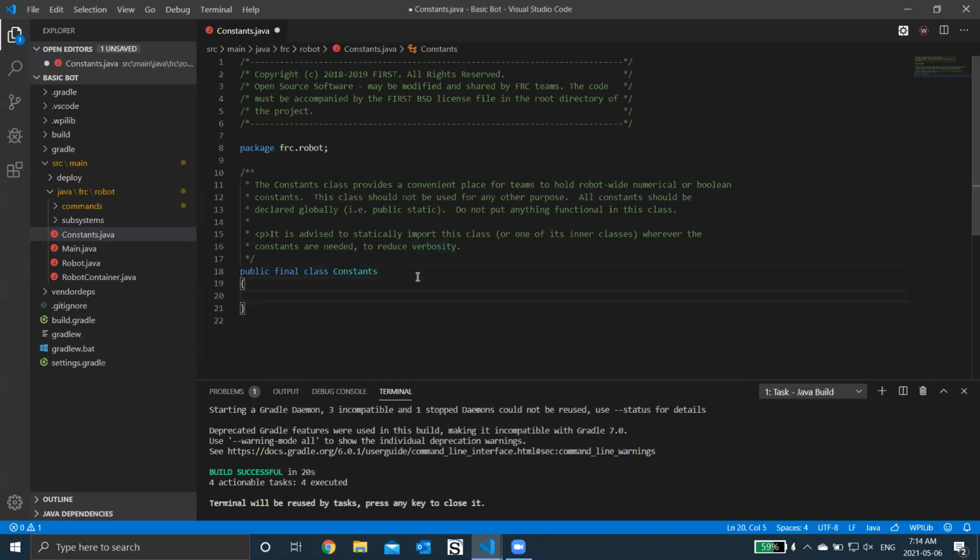All right. So we'll start by setting the CAN ID of the Titan. By default, the CAN ID for the Titan is 42, although if you changed it to something else, then you'd have to put that CAN ID in.